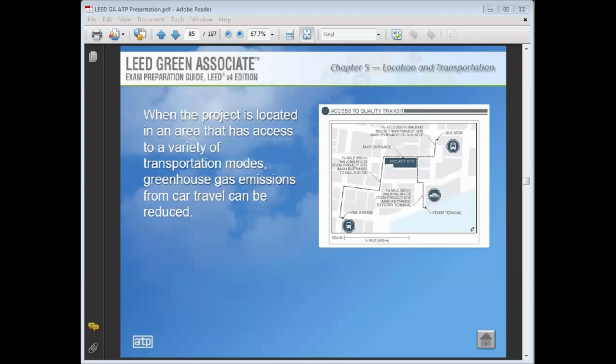Important thing is this, since you will be building a site, you will be excavating a site, that site would not be available or usable for agriculture, forestation, or any other purpose. So if we can add parking to it, it will be more usable, having diverse uses for the same site rather than building a larger paved surface, which is going to create urban heat island effect. Means it is going to absorb a lot of heat. Because of that heat in the context, you are going to have higher energy needs for the building as well, specifically in the hotter regions. So the more parking that you have, the more temperature rise at that place. And then it has a negative impact on the building facades or the building outdoor spaces. And then you have to replan those things.